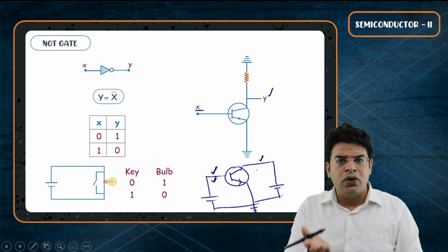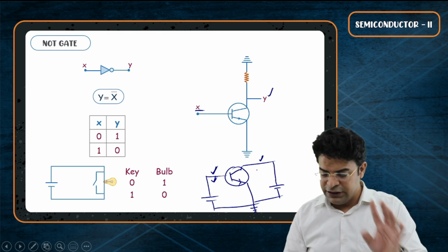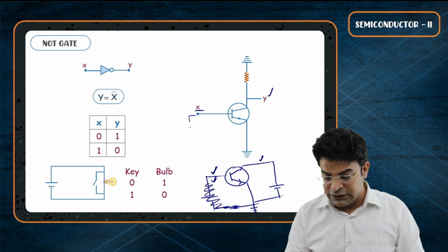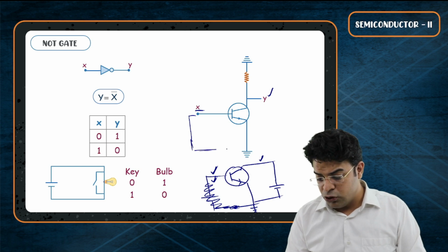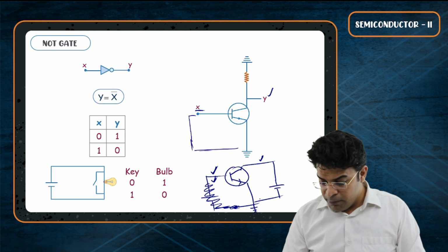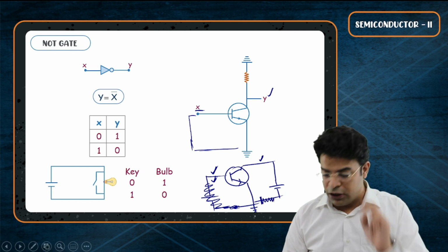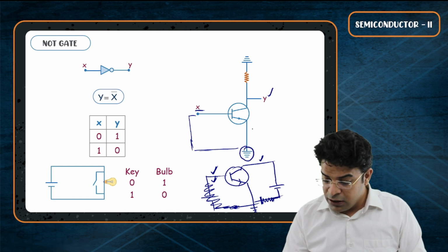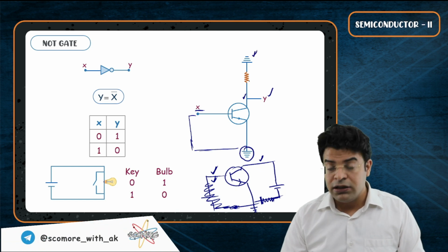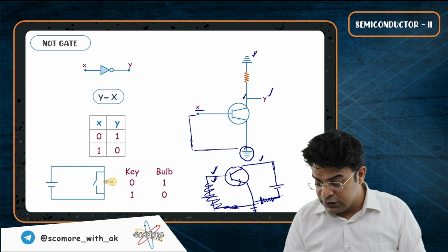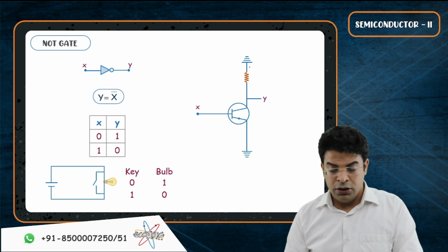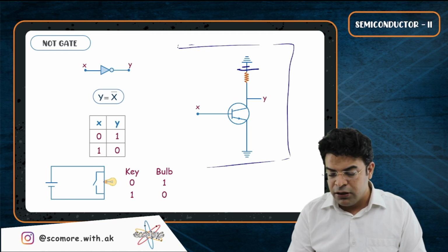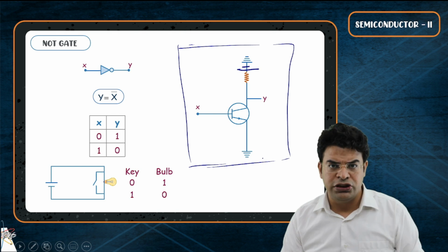But sir, these two do not look the same. They look like different diagrams. See, what they do here is they remove this much part. They do not show us this part of base connected to emitter. And they break it from here and show us two earthings. One earthing here connecting emitter to the earth, and one earthing here connecting the collector to the earth after connecting it through a resistance and a battery. So actually there has to be a battery here as well, and understand that this is nothing but usage of transistor as a switch.